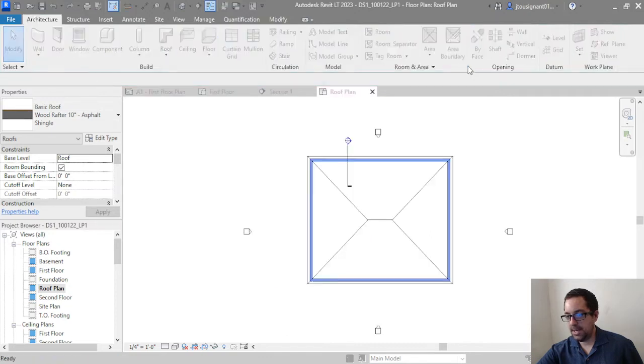And if I press check, it's going to ask if we would like the attached highlighted walls of the roof to attach to the roof. That means, do you want your exterior walls to attach to this roof? This isn't an always attach or an always don't attach. Just like this dialog box isn't an error, which is why I typically never click the do not show me again buttons, because this can be a different answer depending on your situation. So I'm actually going to click attach for this, because in this situation, I will want these exterior walls to attach.